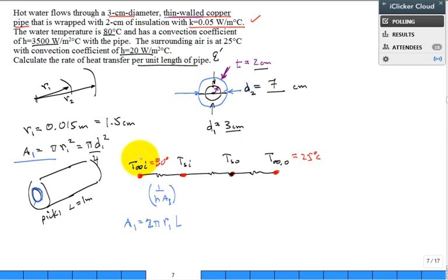Doesn't that give me the area? Is this correct? 2 pi R1 L. Yeah. And then the area on the outside, area 2, would be 2 pi R2 L, and we just worked really hard to get the R1 and R2 squared away in our minds. So this is going to be h on the outside, and this is h on the inside, A2 or A outside, either one.